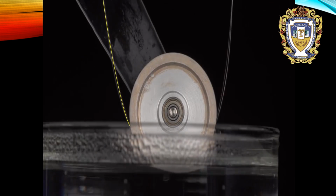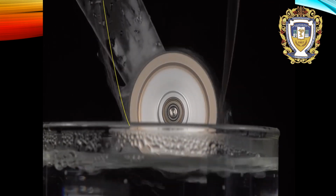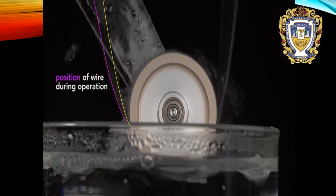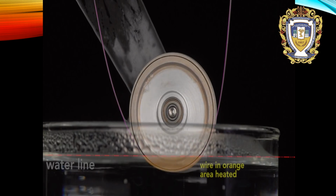Then, when I start the wheel, the wire's distance from the initial position is much greater. It's hard to see, so I'll mark its position with a purple line. This happens because when the bottom wheel comes into contact with the hot water, the section of the wire highlighted here in orange is heated. If it were not in a loop, then the wire would be straight like this. But because it's in a loop, as it tries to straighten, it exerts a force on the wheel, which causes it to turn.